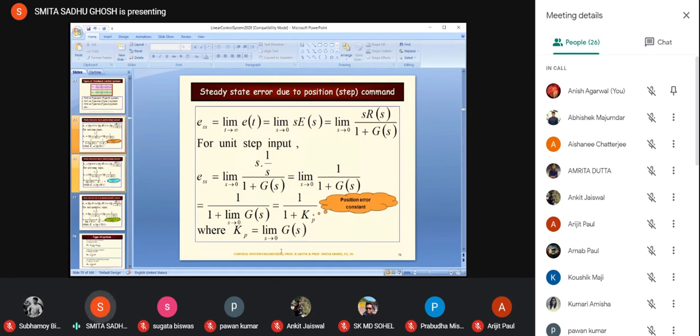So over there, if I just look at the pole placement, whether they are in the right or left, I would be able to see whether it is stable or not. Open loop stability, of course, I'm speaking of right now. Closed loop stability, of course, if you have to find out, you would have to go into your methods of analysis. We are not going to go into the complications of stability analysis right at the moment.